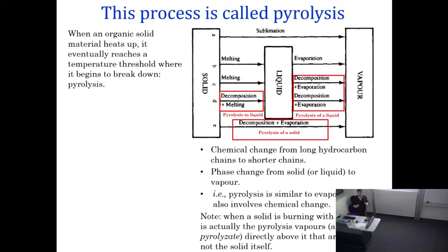Pyrolysis is a central phenomenon in the ignition of a solid. So fires and pyrolysis are very, very closely related to each other, unless you are in a chemical plant where the fuel is already in the gas phase, which typically will lead not to a fire, but to an explosion and a jet fire afterwards. Or even if it's a liquid fuel, you will still have pyrolysis of the liquid because it will not be a pure liquid. It will be a complex organic liquid, and pyrolysis will still take place at the same time as evaporation. Okay? So you have seen this slide already.